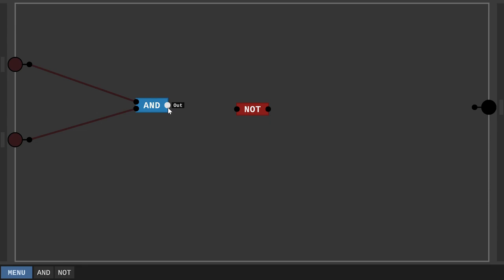For these connections, I'm just left clicking, then dragging and left clicking to release. Sometimes the software won't release, as you're seeing here. It keeps dragging the wire after making the connection. To get rid of that loose wire, you just press escape. Also, after making each connection, make sure that the wire actually releases before making the next connection. Otherwise, you might end up making a bad connection. All right, let's make our last connection to the output. And now we have our NAND gate.